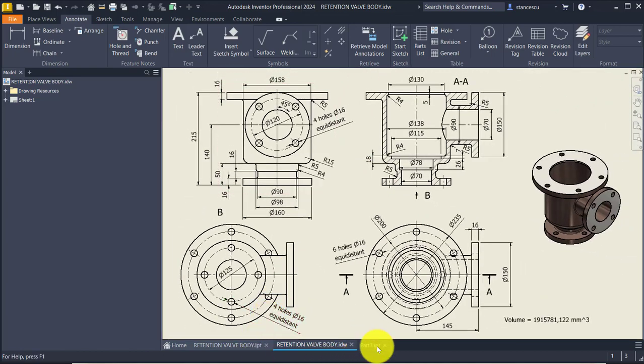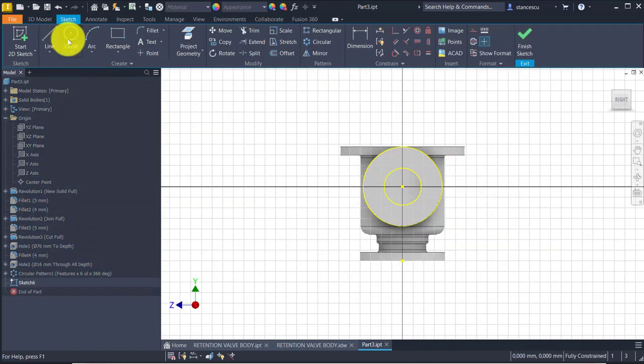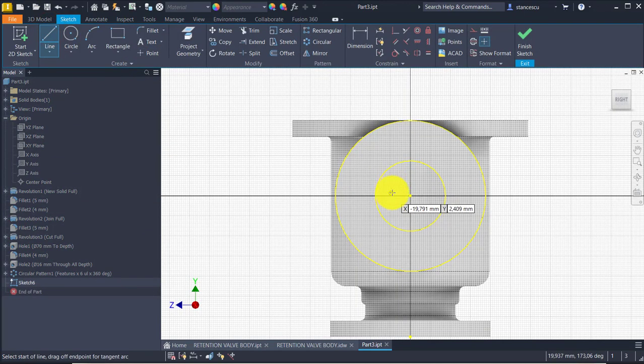Okay, you remember dimensions, yes? I select the plane, I apply a sketch, I activate the tool line, I draw a sloped line with the length of 120 divided by 2, and tab the angle of 45.